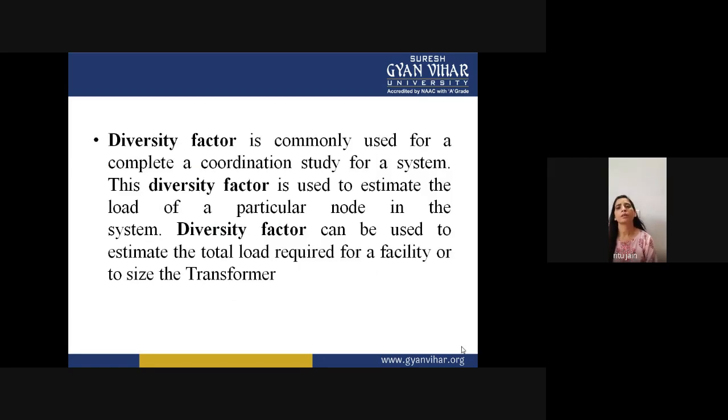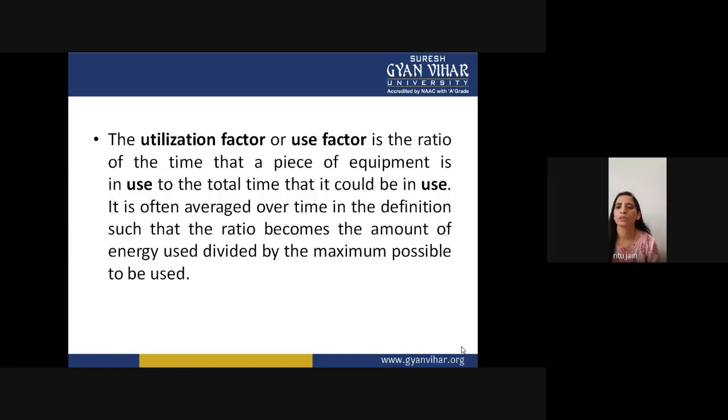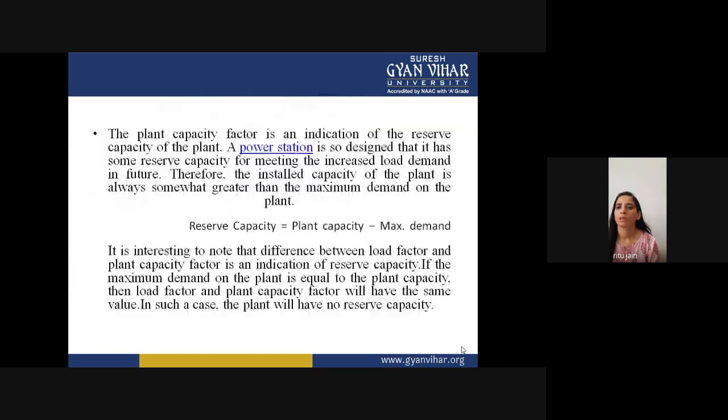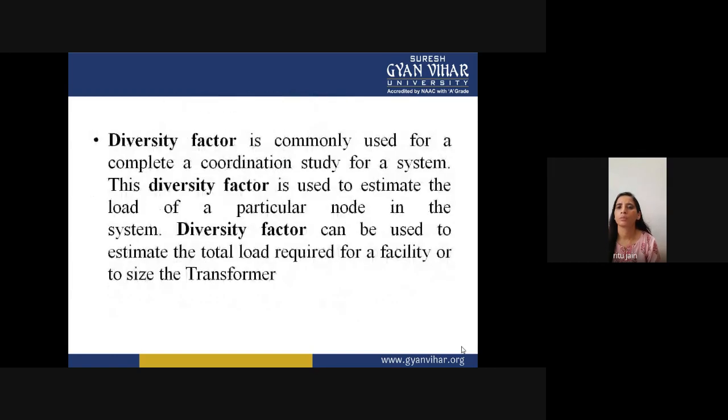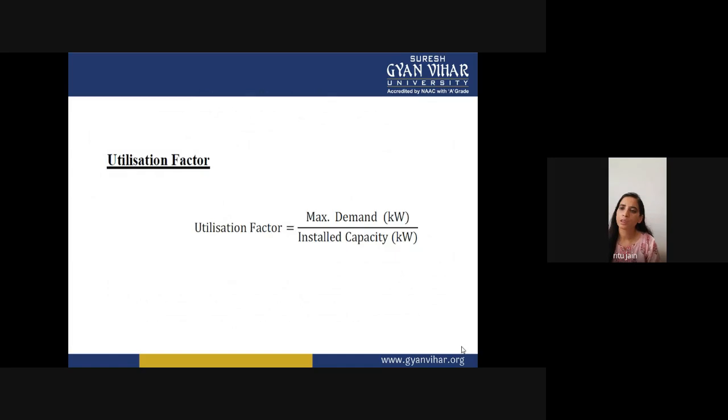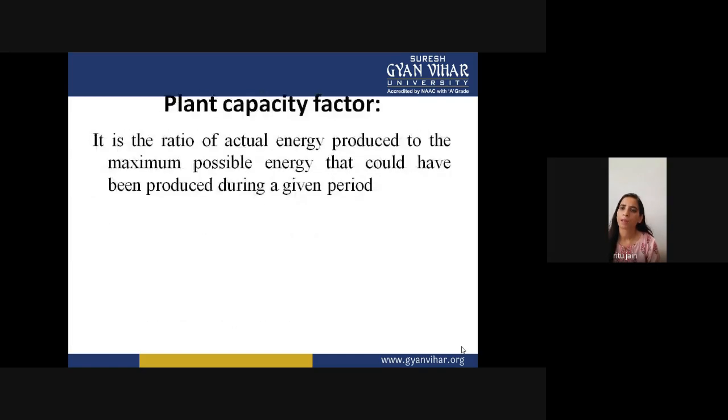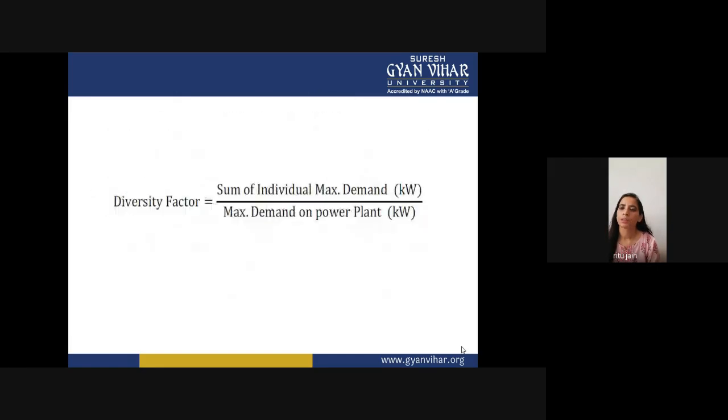Now, diversity factor is commonly used. We have already done diversity factor, but again we can see it because it is very important. Diversity factor is commonly used for a complete coordination study for a system. You have seen in our previous slide that diversity factor is the sum of individual maximum demands divided by maximum demand on the power plant.